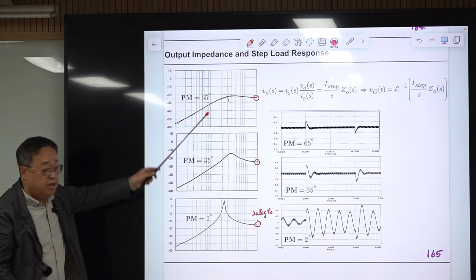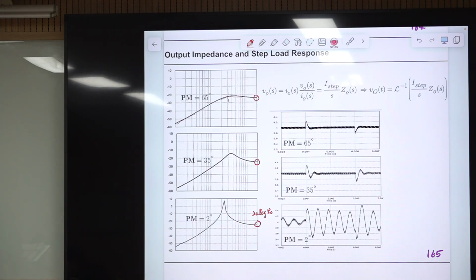And for this case, this frequency is, because there are two slopes, this asymptote and this meeting together. So this pole frequency is the crossover frequency of the loop gain, which is the same as the ESR zero of the capacitor. This is a special case, and for this case, omega c is here.